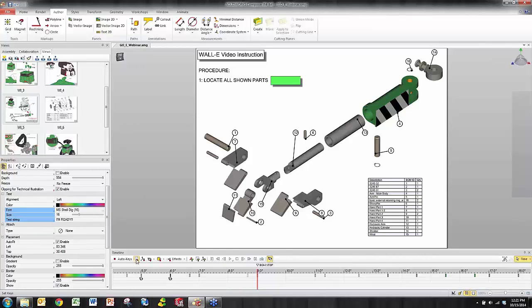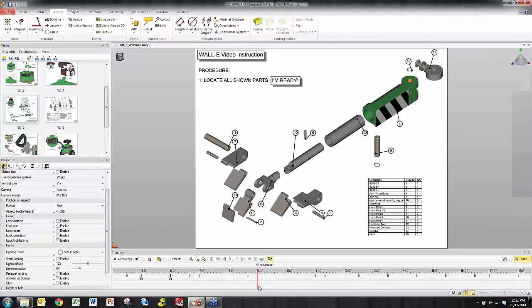Another thing I like to do, if I unselect that and move my time bar backwards a little bit, you'll notice it disappears, right? I'm not in design mode. You'll notice that my button disappears up until it hits that 9-second mark. That's because that's where we changed and recorded all of those specific properties.